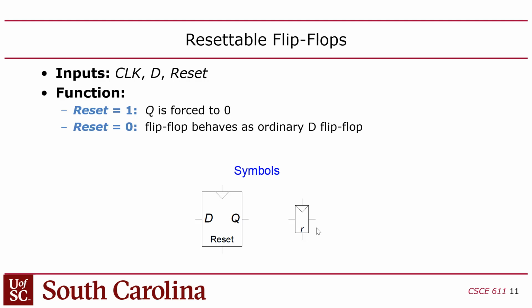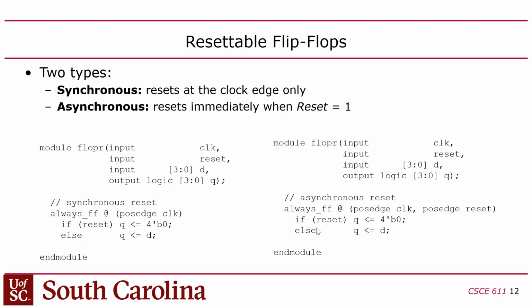You can have a reset input where it'll reset the register to 0. You want to have that for your program counter. So when you reset your machine, your CPU, it should reset the program counter to 0 and start executing instructions at address 0, right? If you don't do that, you probably won't notice, because if the program counter is not resettable, it'll just keep counting and eventually get to 0 anyway, right? So you probably wouldn't even notice if you didn't have a reset on there, but